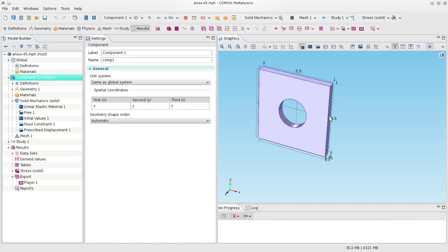This is the front surface over here, and at that front surface I will impose only one condition, namely I'm going to let the plate move and deform in any way it wishes to along the y, that's the vertical direction, and the z directions. So I'm not going to apply any force along those directions. If it wants to, it will be able to deform, but along the x direction I'm going to constrain it to move by the same amount, only along x.